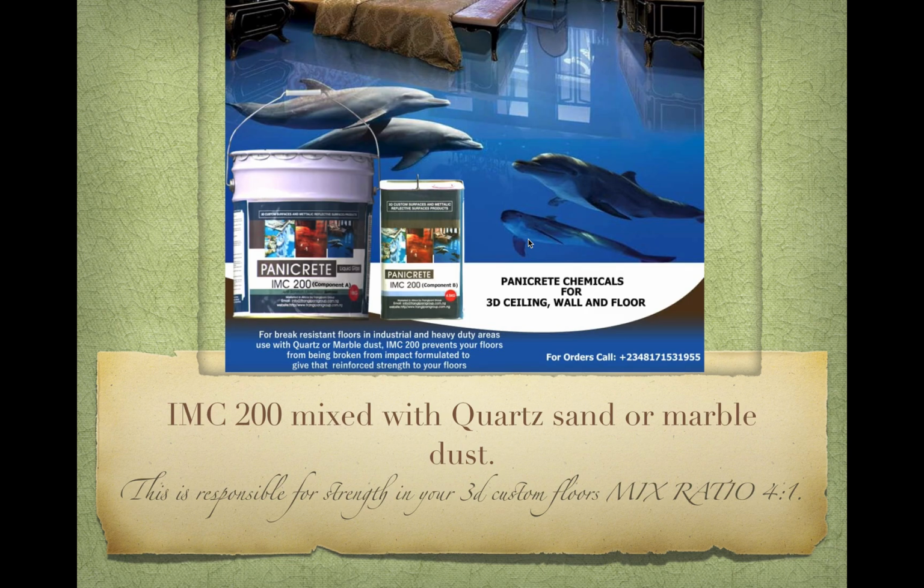Next is the IMC 200. The IMC 200 is always mixed with quartz sand or marble dust, whichever one you can easily source around you. It's responsible for the strength in your 3D custom floors. This also has a mix ratio of 4 to 1. That's for every 4 of component A, you measure out 1 of component B.